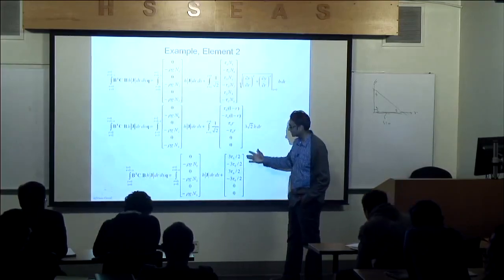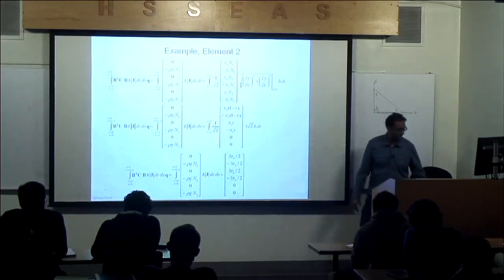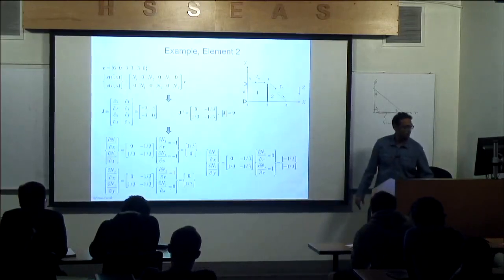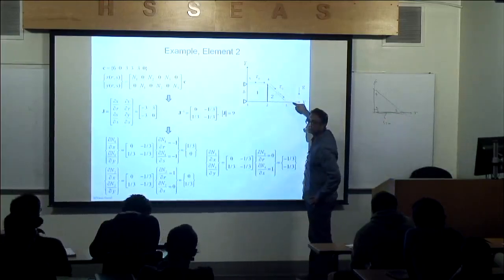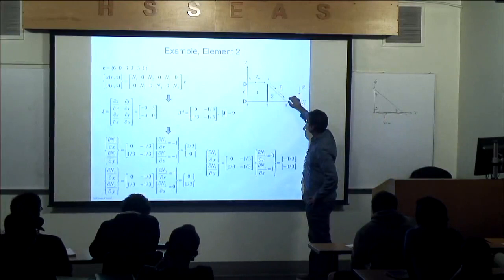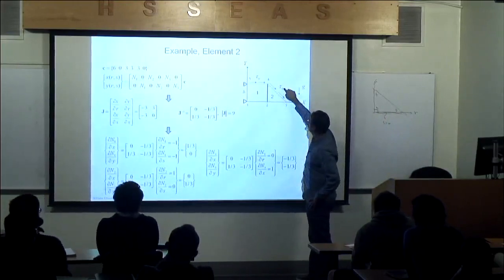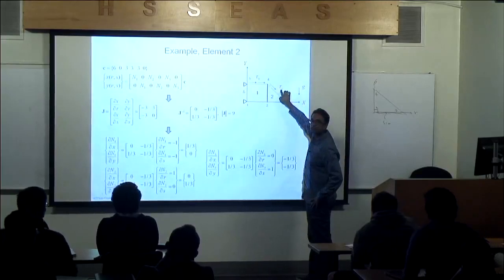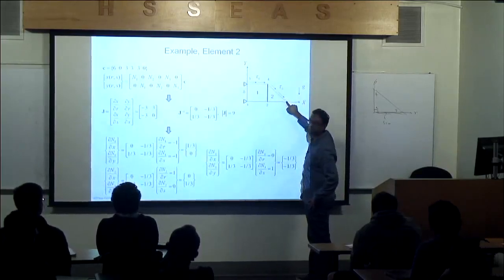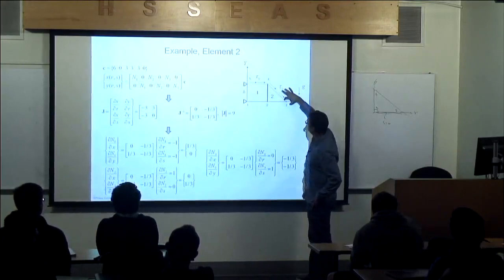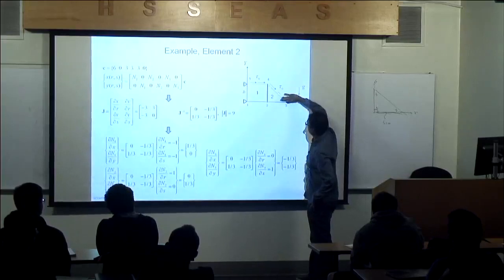Okay? So let's see if this makes sense. We can check that. This length is 3 square root of 2. Agree? So the total force on that surface is 3 square root of 2 times tau 0, right? We'll take half and put it here, and half put it there. But now I have to take that force, which is along here, and decompose it into x and y.